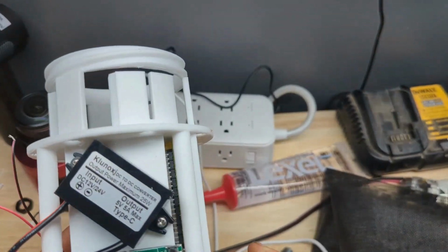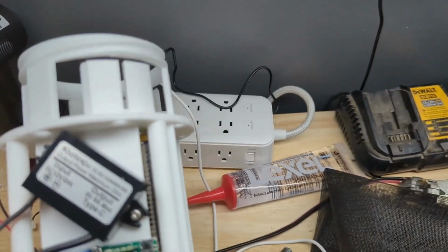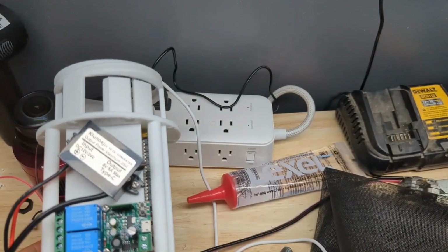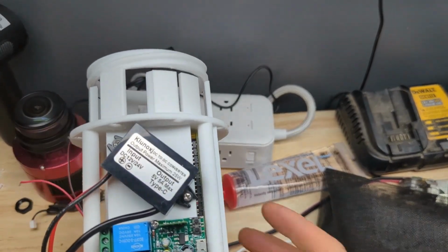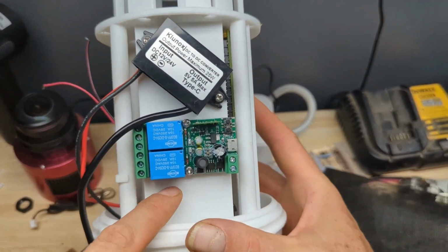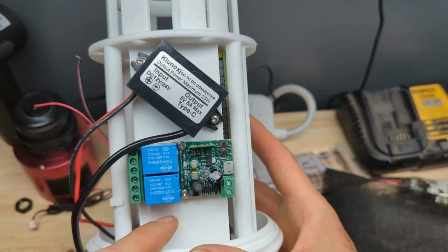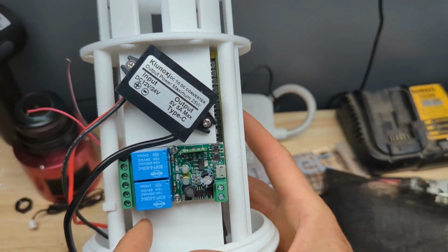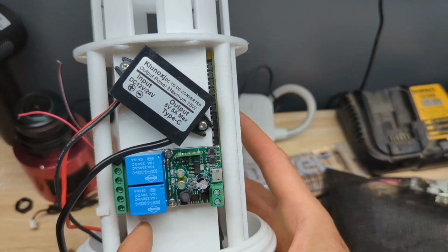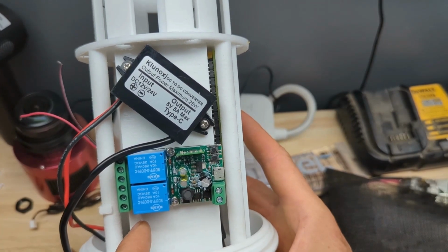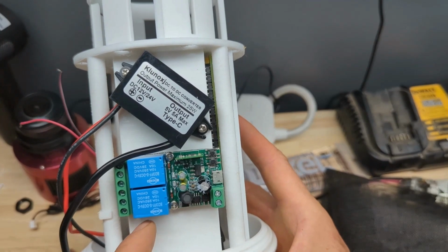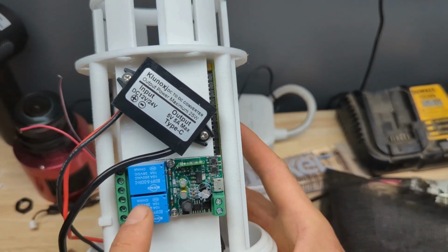And I will mention, I forgot completely to mention this a while ago, whenever you're tapping your holes, use a drill. Don't try to force the screws. Don't just start trying to make your own holes with a self-tapping, because this filament it's plastic, and it can be like wood, and it can split. So if you're too close to the edge and you try to force a screw in, there's a good chance you may crack that out. So go ahead and use a drill to drill your hole, and then use your M2 thread or whatever type of screw that you're using for your components.